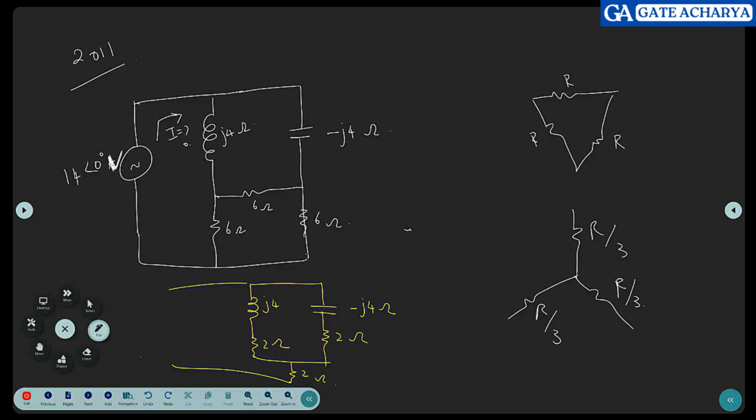How will you handle them in complex numbers? Make them a single impedance, add it to the 2. So this will be 5 ohms. Okay. This is something that you should know how to do. So net resistance is 7 ohms.